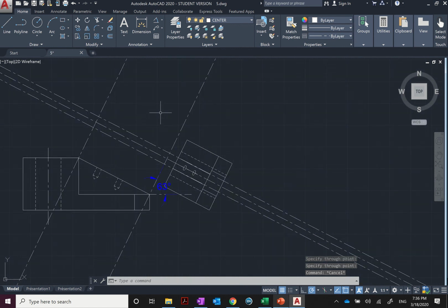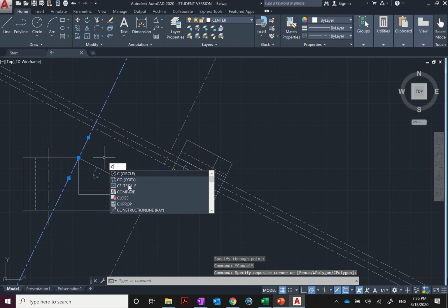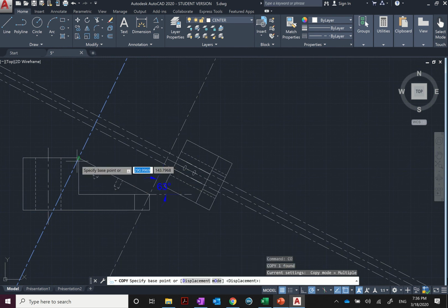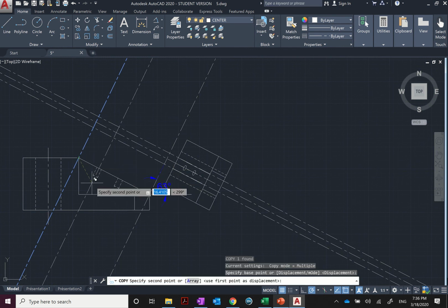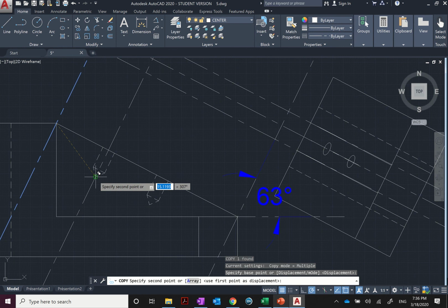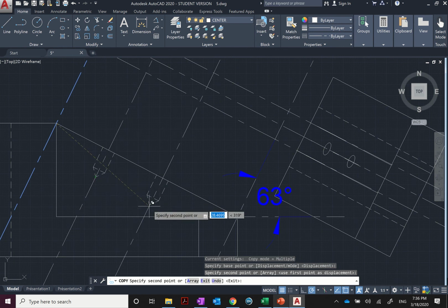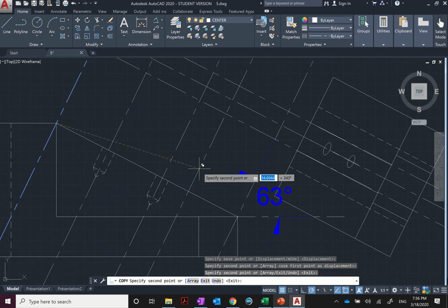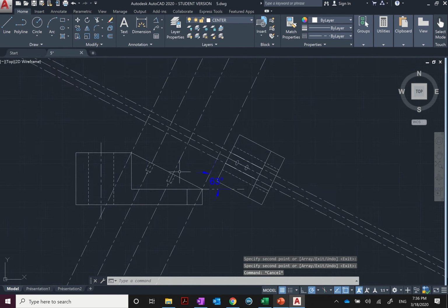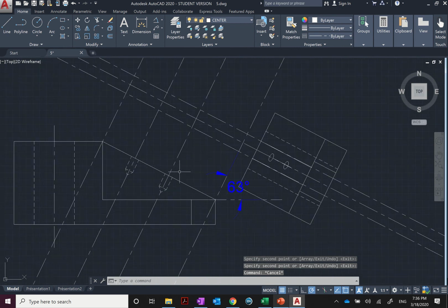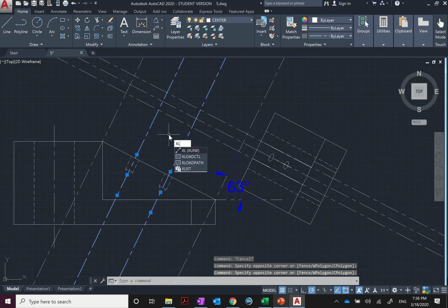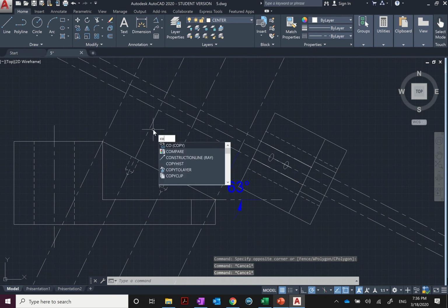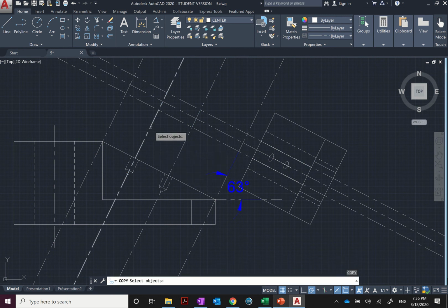And now it's time for trimming and cleanup. Oh, I need two more X lines, so I can go here and copy this one, and move it to the center of the hole, and then one more in here to the center of the hole, and then enter. To know the diameter of these holes, I can also project a couple of X lines.